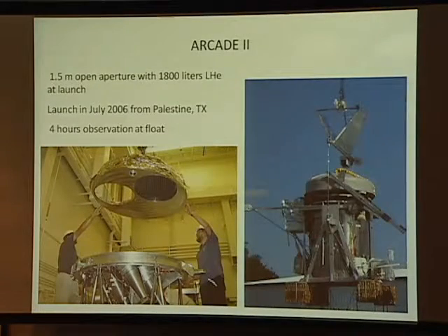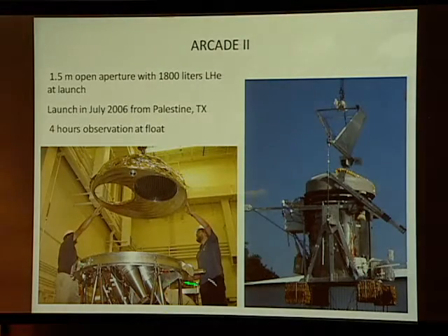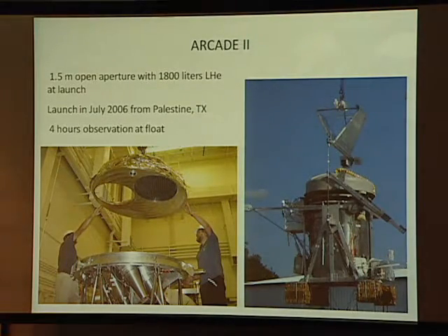Oh yeah, one of the fun things about this is, you have a whole bunch of liquid helium here. It's boiling off on the ground because it's Texas in the summertime and it's 90 degrees outside and 90% humidity. So you get a lot of boiling helium, and that boiling helium turns into cold helium gas, which has to go somewhere. And the real trick is to have it go somewhere without freezing everything, without turning this top section into a solid block of ice, which would then prevent the lid from opening.